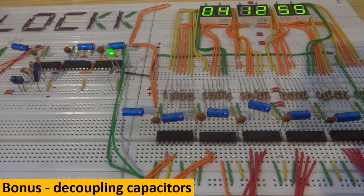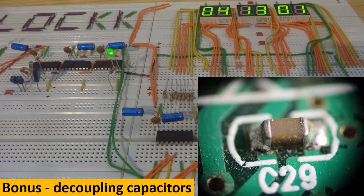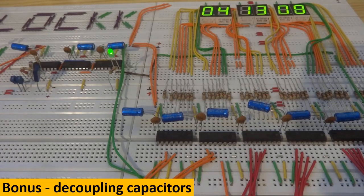You can find plenty of ceramic capacitors on the computer motherboard PCB, but smaller ones in SMD packages. Those, the blue ones, are electrolytic capacitors of bigger capacitance, but with the same functionality to reduce noises on the power line. They are not as critical as the ceramic ones.